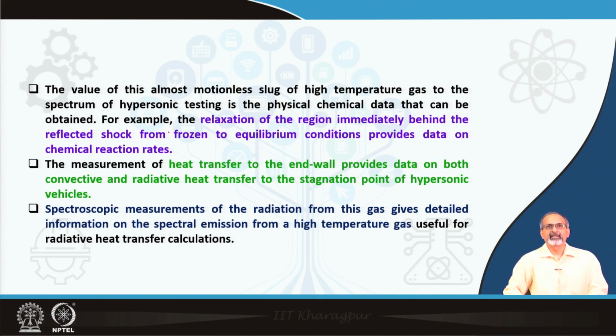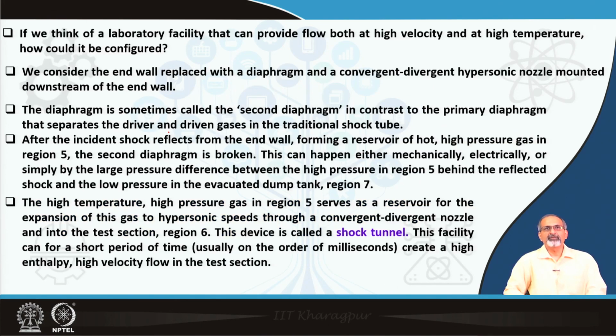There is still more to it. Spectroscopic measurements of the radiation from this gas gives detailed information on the spectral emission from a high temperature gas. So, there are multiple applications of this. Further, it can be used for running a very important facility which is called a shock tunnel, where we basically make use of this high temperature, high pressure gas to be subsequently expanded through a CD nozzle into a test section by means of a second diaphragm that we open up at the end wall.